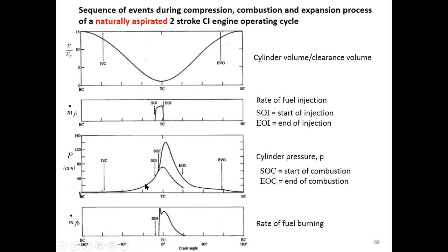Okay, and then up to here, before the piston moves up to the top dead center, we have the start of injection, SOI, here, right? But the fuel is still not burned yet. Why? Because we see that the pressure is still on track with the motoring curve.